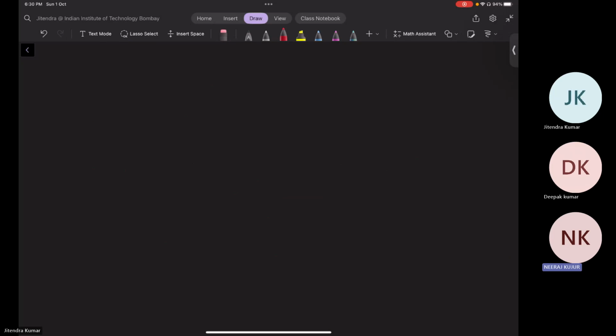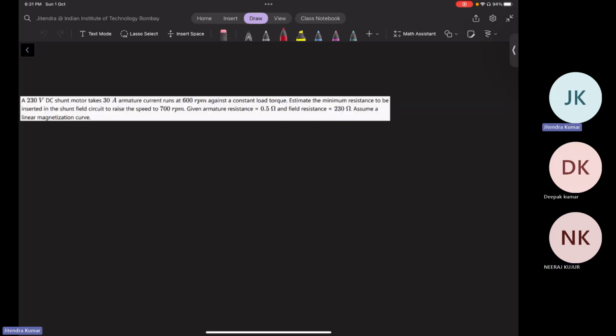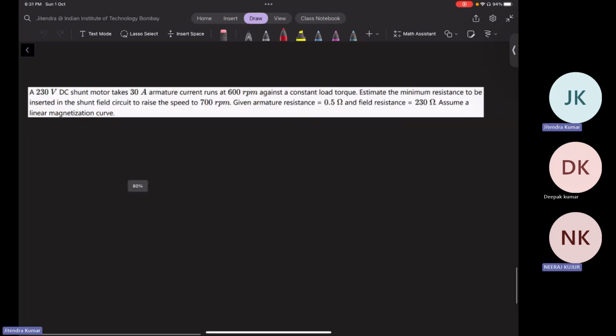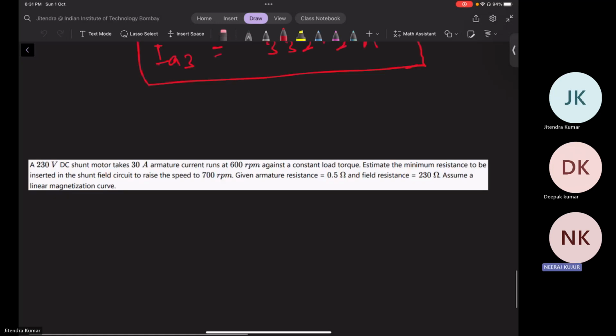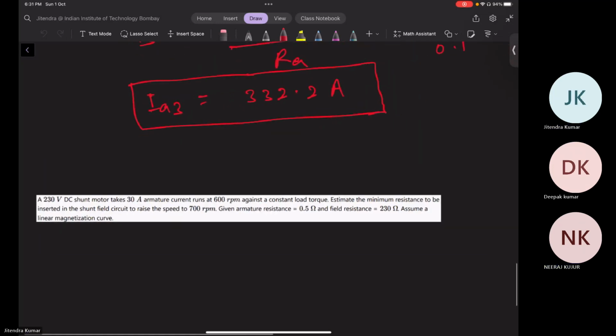Any question, Neeraj? Is there any possibility of damaging the windings due to these high currents, sir? Definitely, there is a high possibility of getting damaged. That's why, as I mentioned in between, we use series resistance, to limit that current. Though it will reduce your performance by a small margin, it will protect your motor.